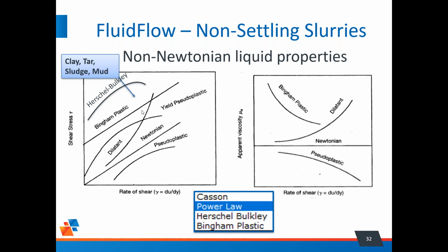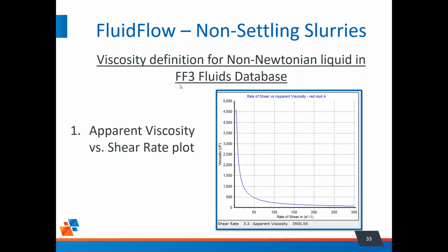Most commonly, these are the ones that FluidFlow has: Herschel-Bulkley, Power Law, Casson, and Bingham plastic models. These are the most common rheology models, and we have the ability in that case to define this viscosity in the fluids database in a couple of different ways.